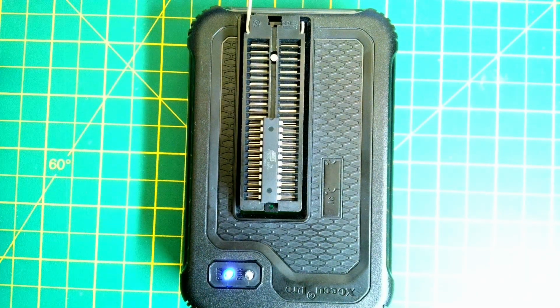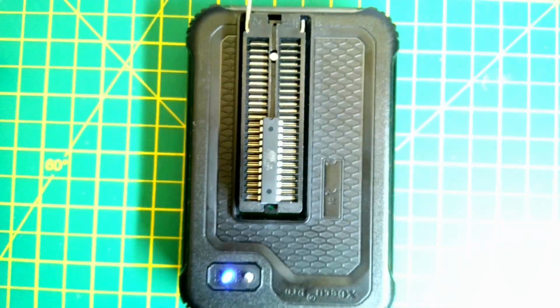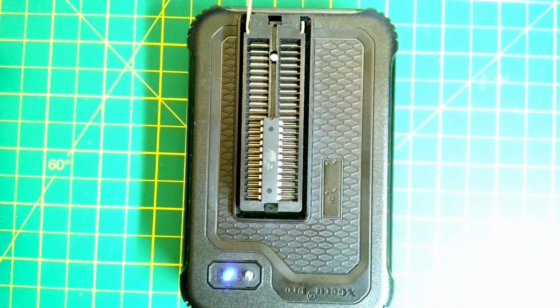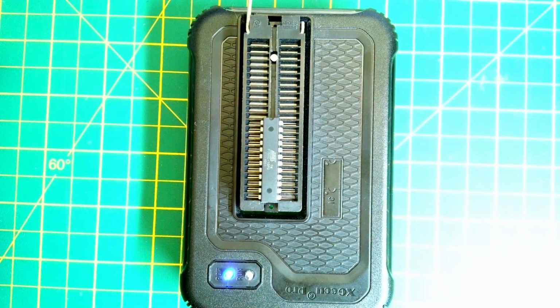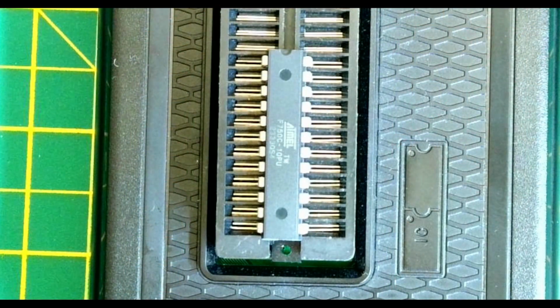So if you see here, this is the T56 programmer, which was the more expensive version. Certainly when I bought it during the chip shortage, it was probably more expensive than it is now. I believe there is a new version, something like a T76, which is being advertised now. I haven't seen anywhere on Amazon where you can get this. And if we just have a quick look at this, you can hopefully see this is that Atmel ATF750C 10PU. So that's what I'm going to be looking at in the next video, and this should really allow us to do some much more interesting things with the PLDs.